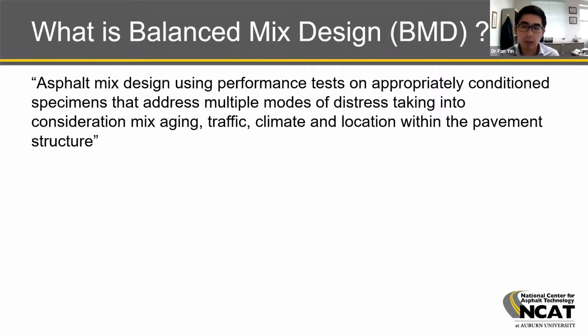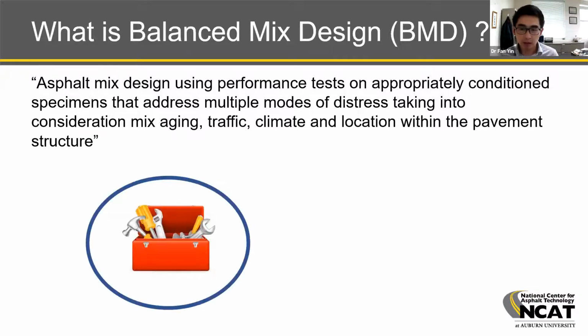If we look at the definition, balanced mix design refers to asphalt mix design using mixture performance tests on appropriately conditioned specimens that address multiple modes of distress, taking into consideration mix aging, traffic, climate, and the location within the pavement structure. So the way I understand this definition is that balanced mix design is a toolbox.